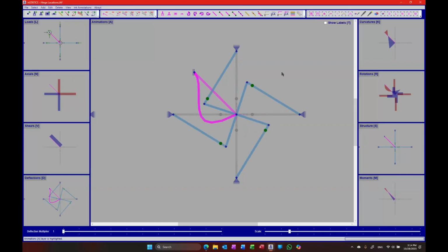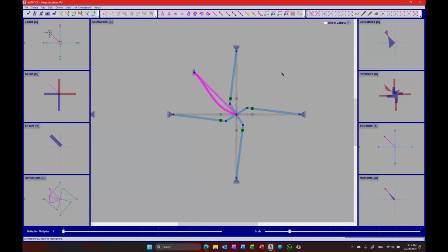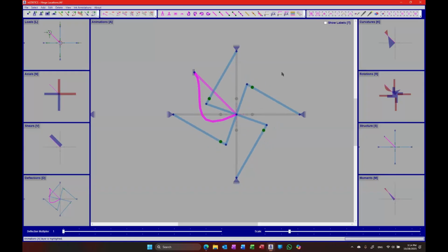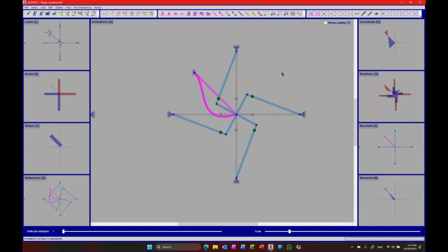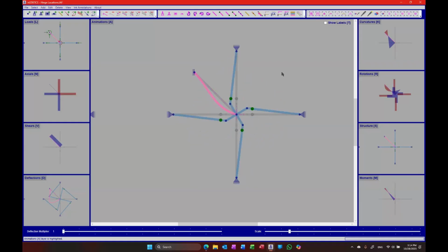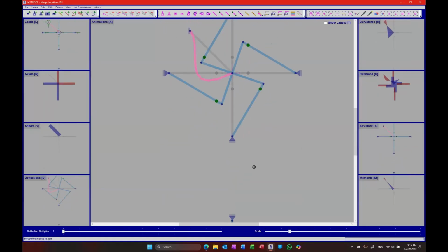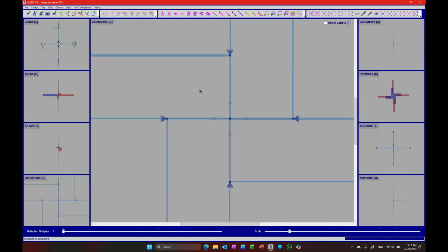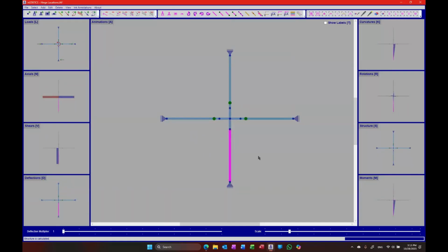So you have to be very, very cautious. Always look at the deflected shapes, because those soft springs are, as the name implies, soft enough that you can still see the load flow. Basically, the load flows, but you also will have large deformations. So be careful about that. But yes, you're right. This is the reason why we have one of those hinges not added, because otherwise your joint becomes a mechanism.